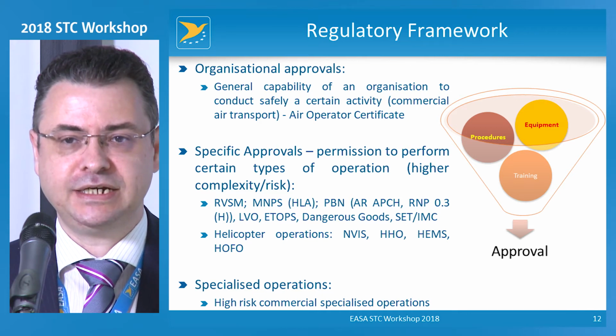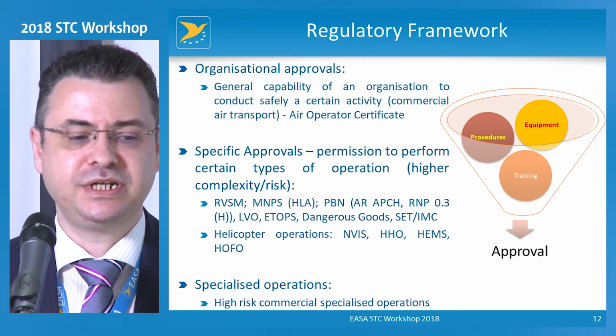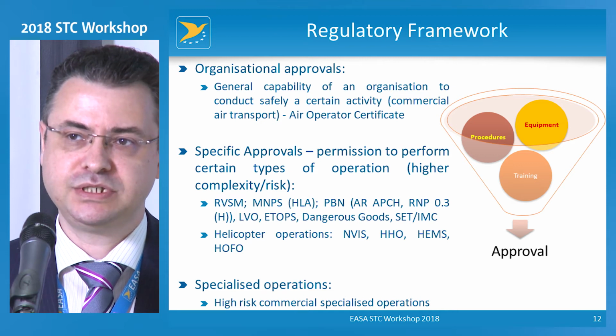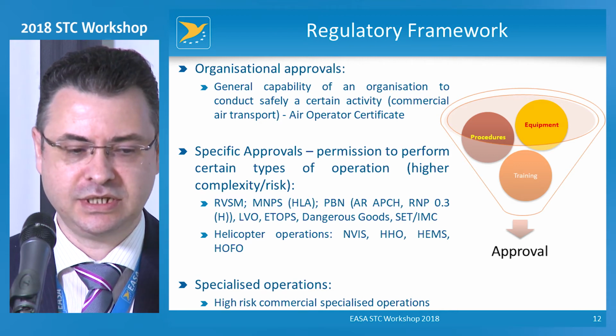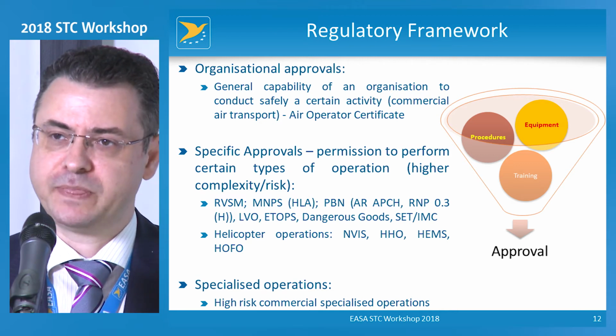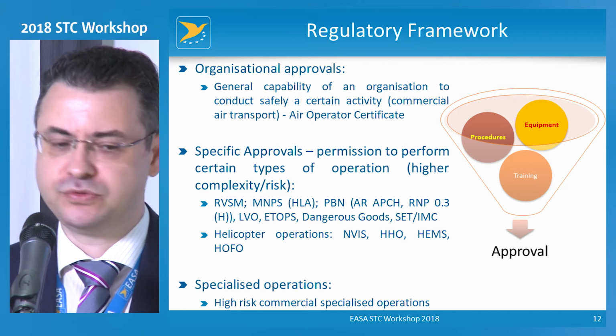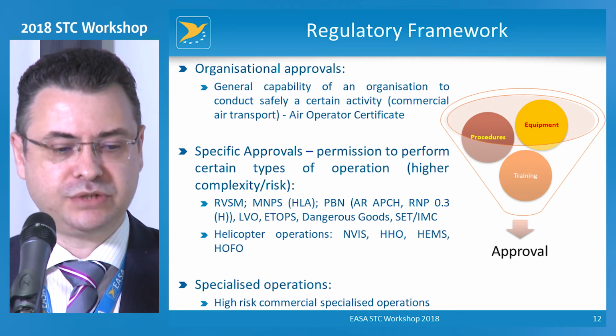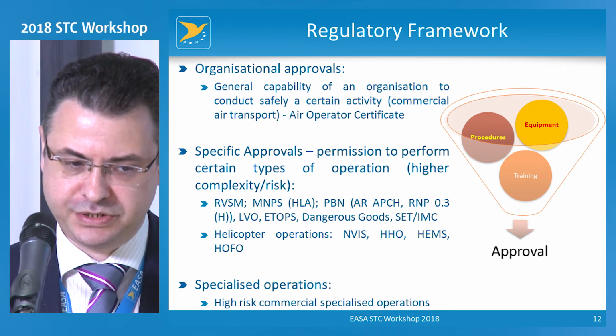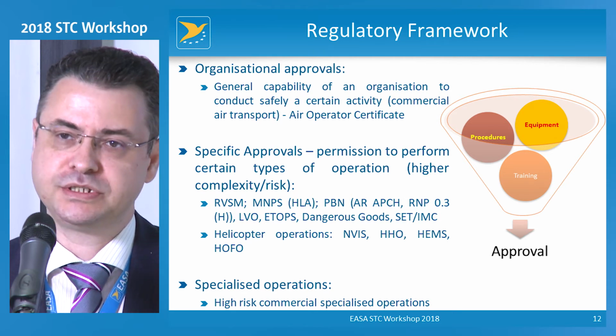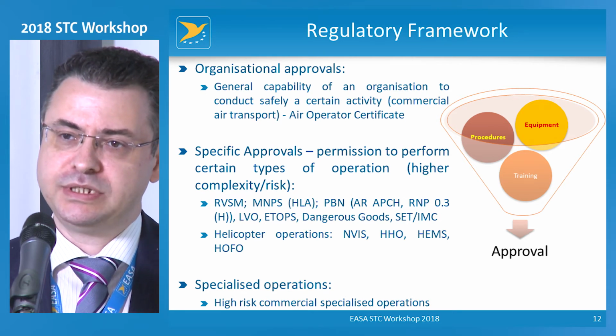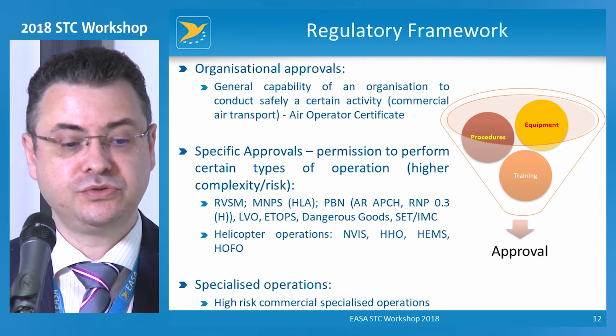However, they are not sufficient in themselves. You need to consider a number of other aspects as mentioned, in terms of operating procedures, training of crew, MEL consequences, and so on. ETOPS operations, so operations with twin engines with extended diversion times, dangerous goods, and the new one we just introduced in Europe last year, operations at night or in IMC conditions with single-engine turbine when engaged in CAT operations.